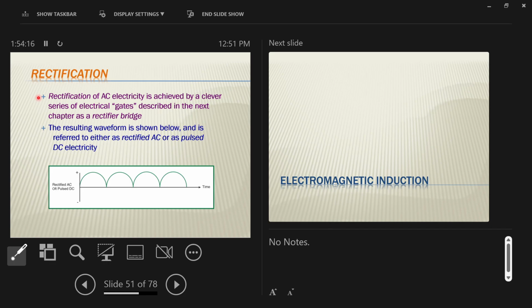All they've done here is taken those negative pulses and flipped them. Okay? Using a series of diodes in the system, we've tricked the electricity to always move in one direction. Okay? Electricity is not that smart, we can outsmart it, and we did. This is called full wave rectification. To be specific, if you've already gone through the book, this is called single phase full wave rectification. Okay? I won't talk about phases today, that'll come next time. But yeah, full wave rectification.